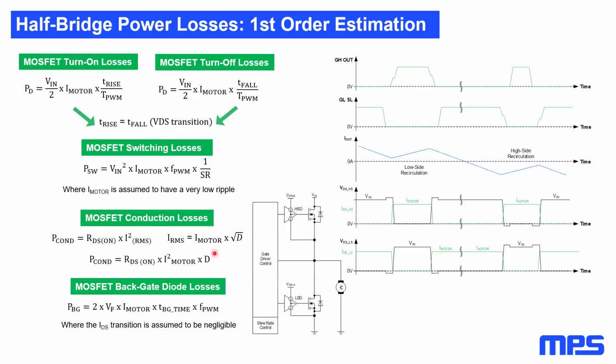Okay, one new question came in: how can we estimate power loss in a DC link capacitor due to ripple current? Well, first of all, you have to know your capacitor. So the ESR, and maybe the parallel discharge resistance, but that's a very marginal effect. The main effect is on the ESR, and so they are basically conduction losses.